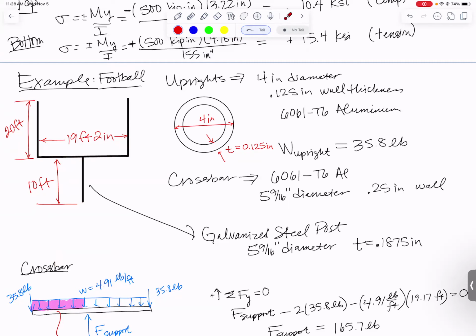Well, we could analyze and figure out the static stress right there. I don't think that it's terribly relevant for updating our analysis right now, and here's why. So first of all, that area right there, if you get this rocking back and forth, it's going to be experiencing both bending and torsion at the same time, so a fairly complex stress state.